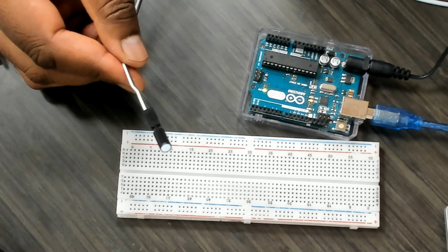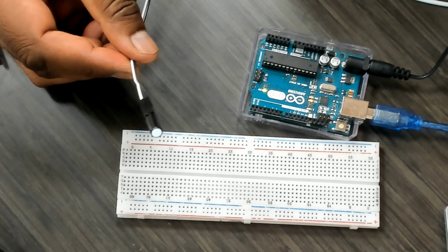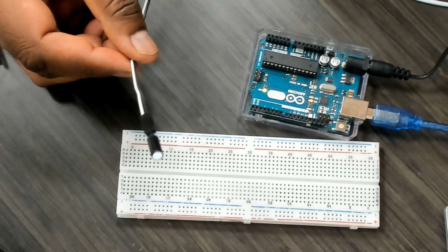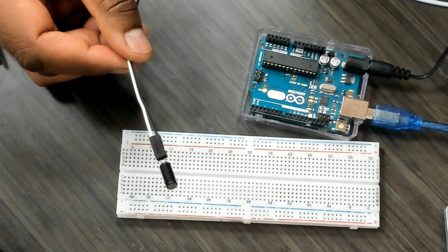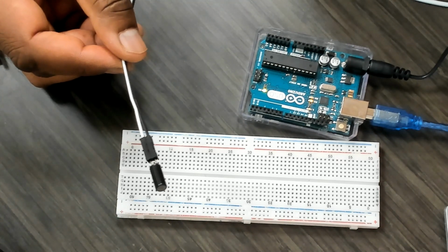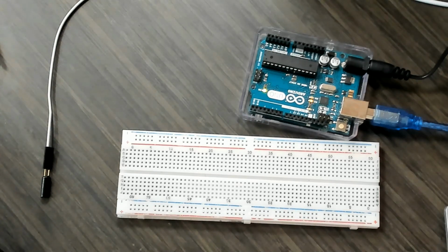And this switch will either apply 5 volts or apply 0, and change the voltage so that we can read that. You can't leave a digital pin which you're reading just open. That's not going to happen. Okay, so that's what we'll do. We are going to pull down using a 10K resistor.